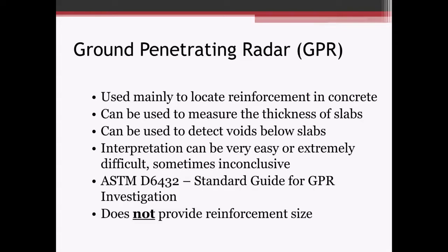So next we'll talk about ground penetrating radar. We use this quite a bit in the industry, mainly to locate reinforcement in concrete, but we can use it for other things. We can figure out the thickness of a slab because we typically get a really good reflection off the bottom of the slab. I'll show you that here in a minute.